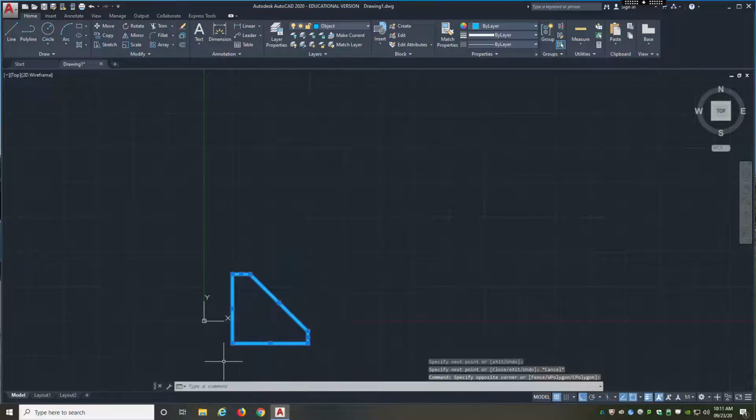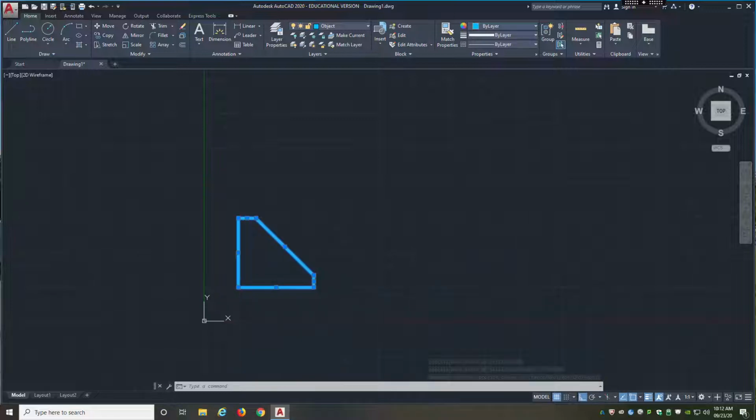And what I'm going to do is I'm just going to select everything. I'm going to hold control and then use my cursor arrows here to place it in that first quadrant, hitting escape to get out of it. Okay, so based on some of the information that we have here, what we need to do is use construction lines effectively to get some of the information from one view to another view. So in this particular view, this is really all I can do with this information.